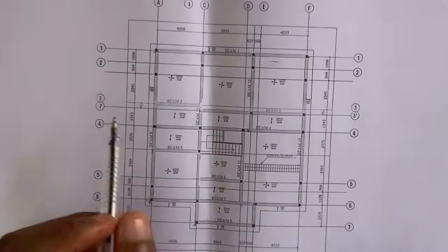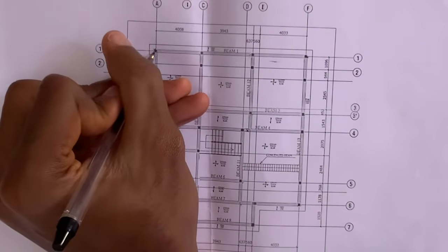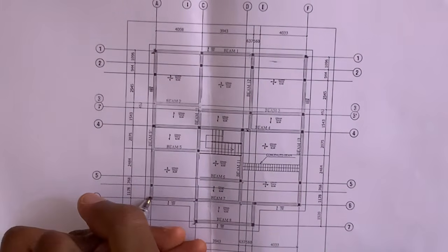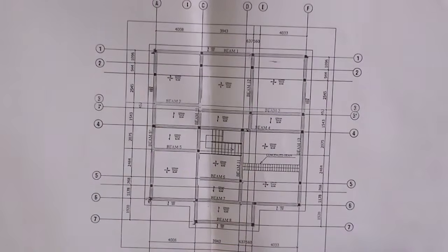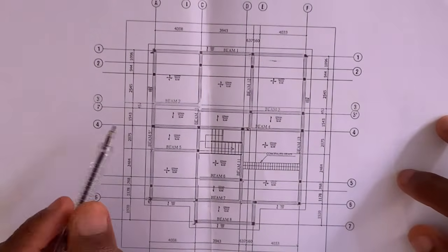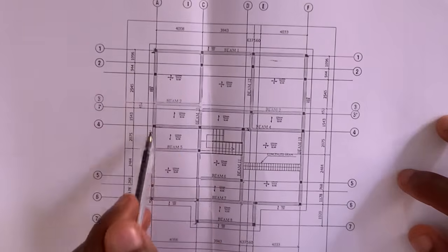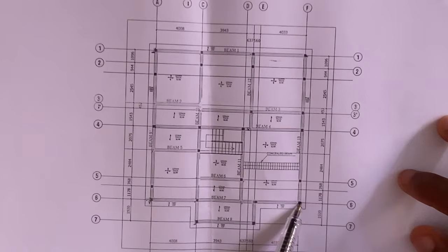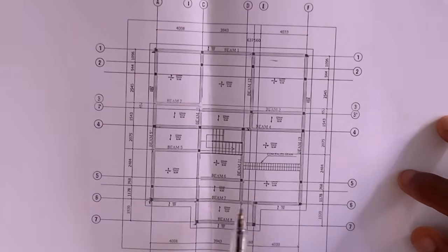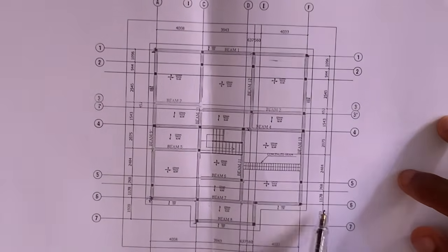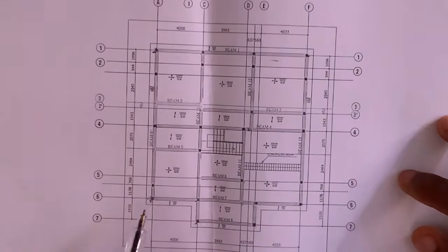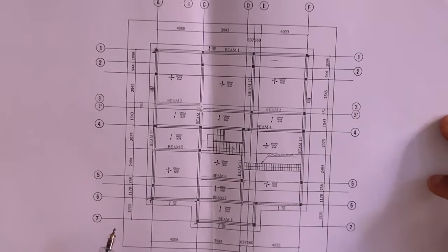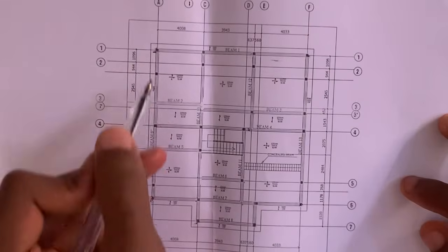So now it means that what we've measured now is this internal point down to this internal point here. Now what can you see in this drawing? You can see that what we have here will be the same thing as what we have here, because they are equal and opposite. Remember, beam 1 and beam 7, we catered for it to be out to out. We are not going to cater for this one to be out to out again, because we have it to be over measurement. So this point now will have to be what?